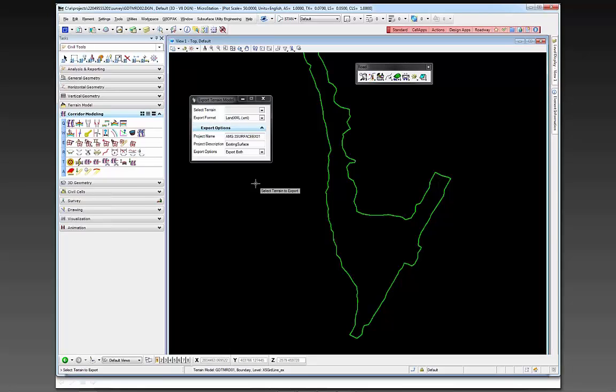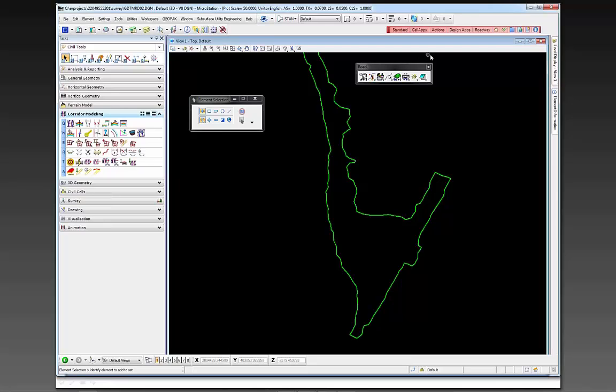I wish that the proposed surface was that easy, but it's not. So now we're going to talk about the proposed surface. And what you'll first need to do is you'll have to create a sort of intermediate file, because we have all those break lines, and there is no terrain yet. All there is corridors and an intersection terrain.